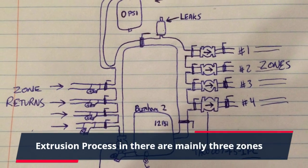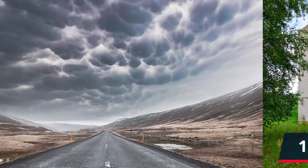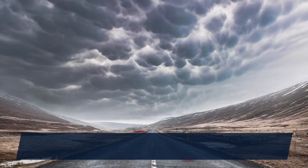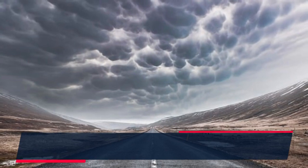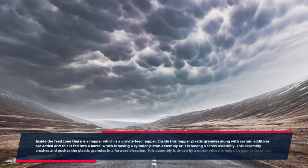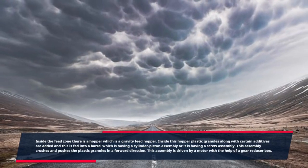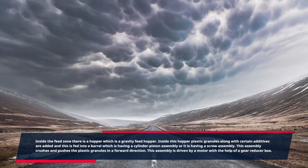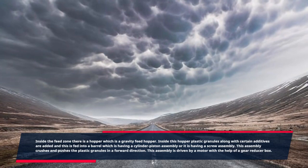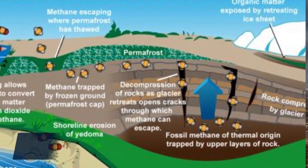In the extrusion process, there are mainly three zones. 1. Feed zone. Inside the feed zone there is a gravity feed hopper. Plastic granules along with certain additives are added to this hopper and fed into a barrel which has a cylinder piston assembly or a screw assembly. This assembly crushes and pushes the plastic granules in a forward direction. It is driven by a motor with the help of a gear reducer box.